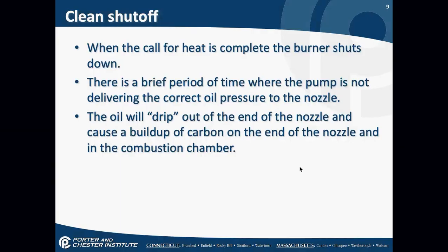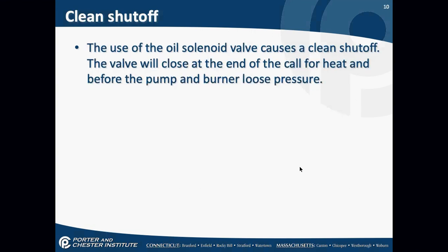Clean shutoff. I talked about this a little bit ago. When the call for heat is complete, the burner shuts down. There's a brief period of time where the pump is not delivering the correct oil pressure to the nozzle. That oil is going to drip out of the end of the nozzle and cause a buildup of carbon. It's what I talked about earlier with the air in the system as well. Same thing happens. As the oil pressure drops from 100 psi to the 70 psi where it should hold, there's going to be a brief period where the oil is not going to spray properly into the combustion chamber.